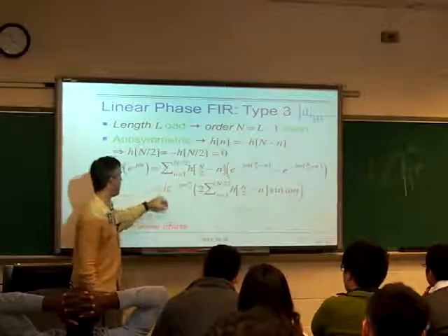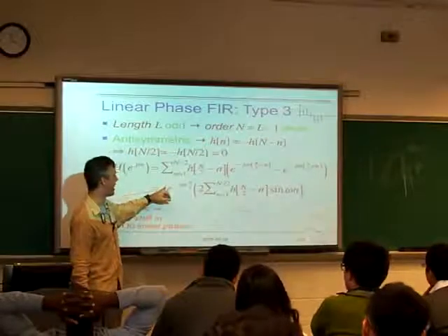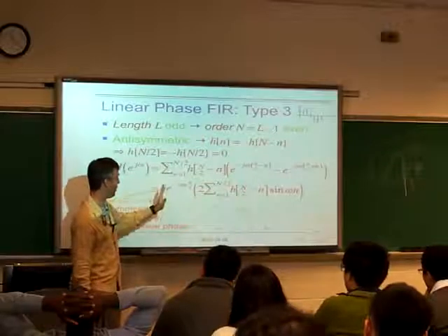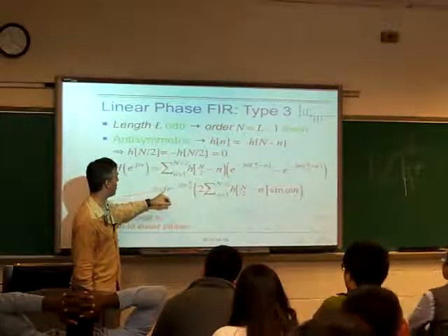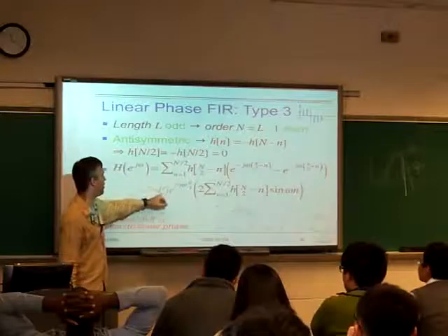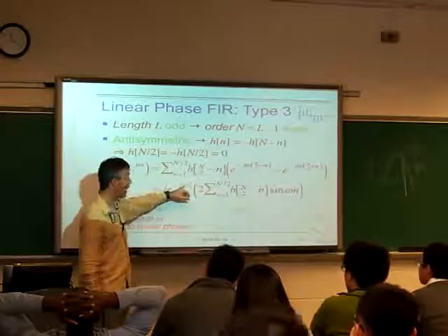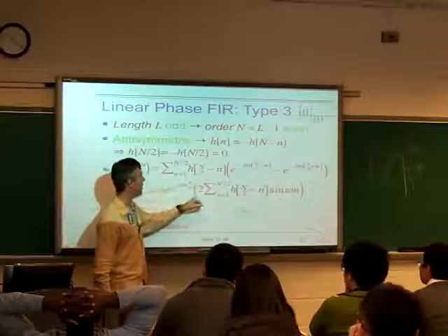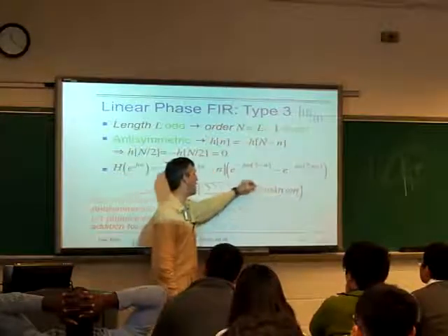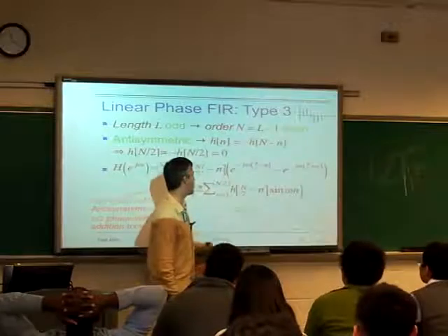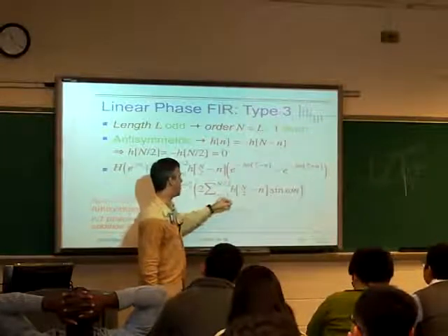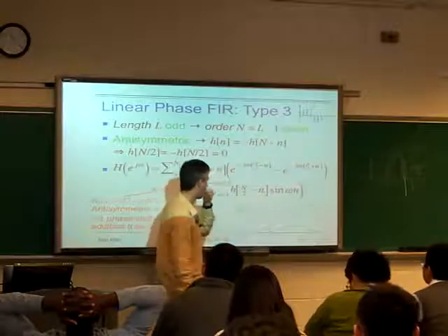And we get a j coming out, a constant j, which is also just a pure phase term, right? It's a pure pi on 2 rotation. So here's our phase term, whose variation with omega is linear, but it's not proportional to omega. And then here we have the pure real magnitude response part, which is built out of sine functions starting with sine omega.